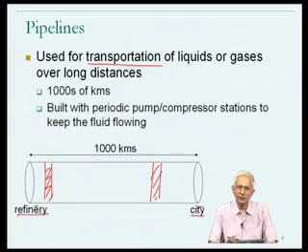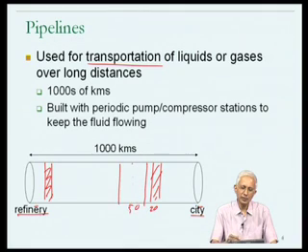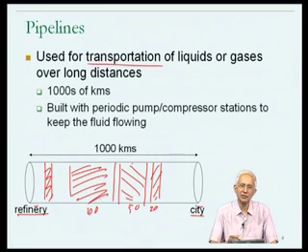A much more effective use of the pipeline might be that after having pumped the 20 kilometers of airline fuel, I conceivably have to leave a little bit of a gap, but I could then pump maybe 50 kilometers of some other fluid, maybe diesel, through the same pipeline. And after maybe a little bit of a gap, I could pump maybe 100 kilometers of some other fraction of petroleum. And in essence, by trying to keep the pipeline full, I'll be increasing the utilization of the pipeline.